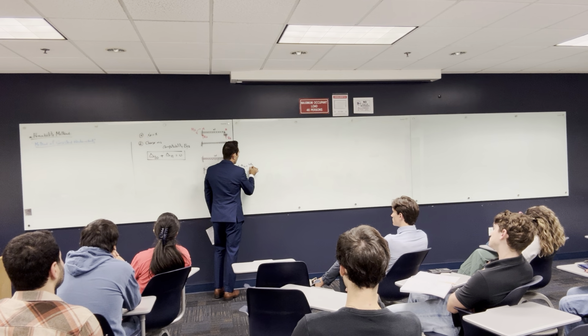And you have to get these points one by one. F1, you are gonna put a unit load at 1. You are gonna put a unit load here. And then the second one, you are gonna put a unit load here. And the third one, you are gonna put a unit load here. And you will try to get the deflection for each one of them.